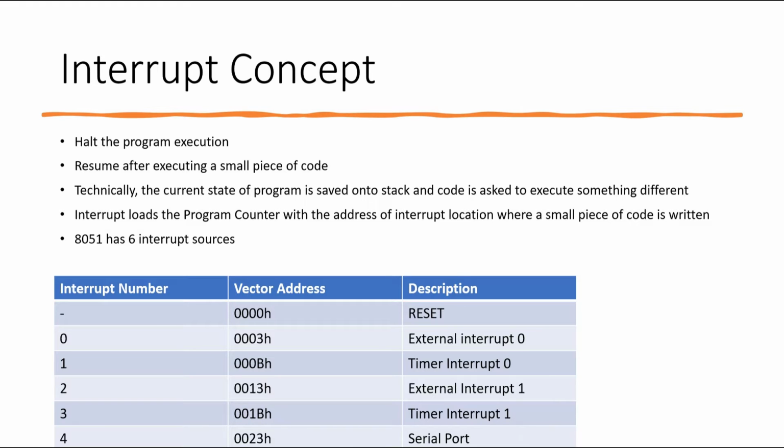Now, if you are creating an embedded system where you have used an emergency switch, and let's say you have built a crane, when you press a button, the crane is supposed to move for 10 seconds. I repeat, when you press a button, the crane is supposed to move for 10 seconds. Now, if I have an emergency stop button, there is no alternative. I don't want those 10 seconds to finish and only then get back to stopping the crane.